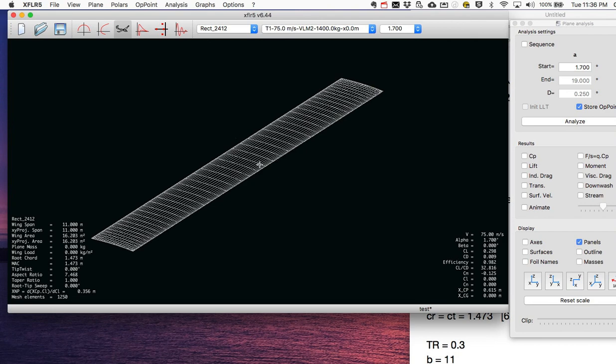It takes that Reynolds number and lift and runs XFoil for this particular foil section, the 2412, and asks it, where is the transition, upper and lower surface? What is the viscous pressure drag? What is the skin friction drag? And it adds it into the total drag. Here it's reporting the total drag coefficient and total lift coefficient on the screen.